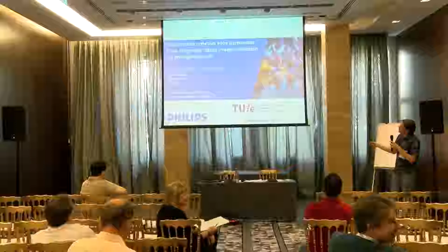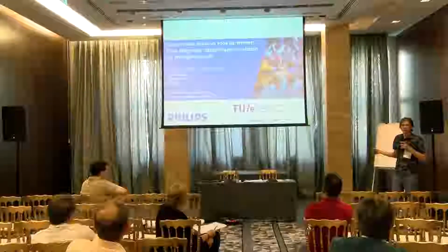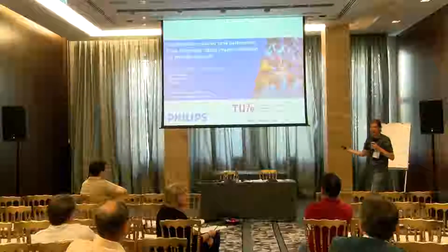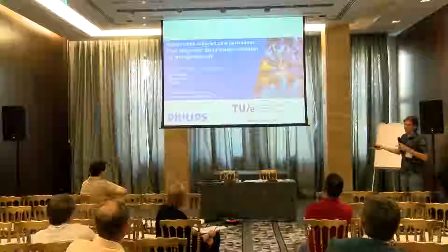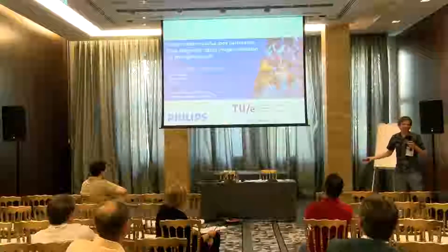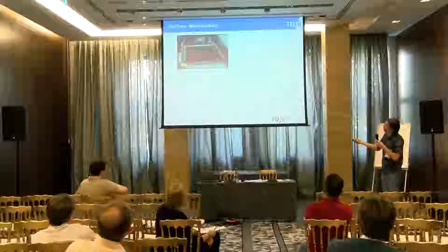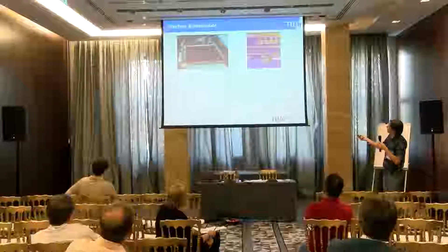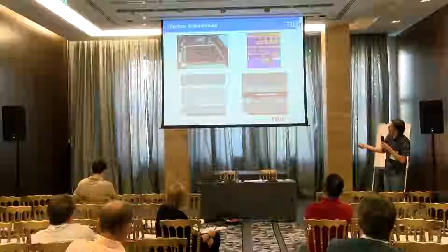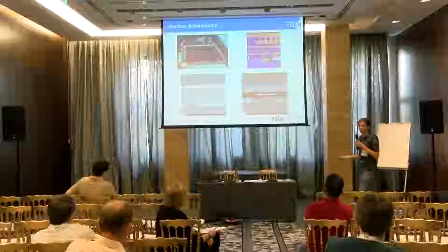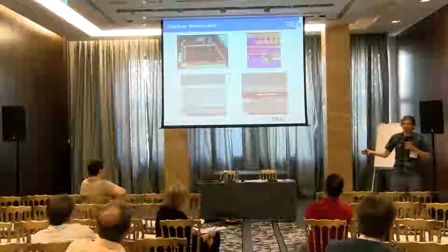So the whole idea is that we want to identify interface parameters, and often you don't have access to forces. The only thing you have is images. I'll have a specific example in microelectronics, but you can think of anything like a bridge or whatever. My motivation comes from microelectronics. We look inside, there might be a delamination going on at a certain location, and there's no way that you know exactly what the loading condition is. But we can do some kind of test and see a delamination under a microscope occurring.